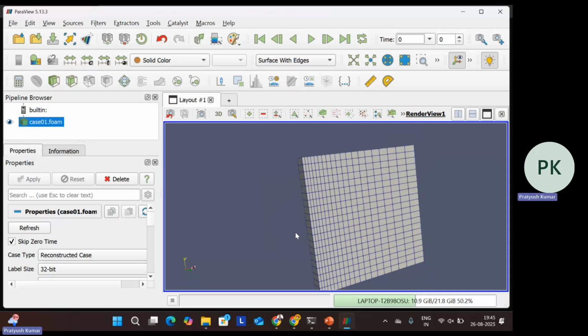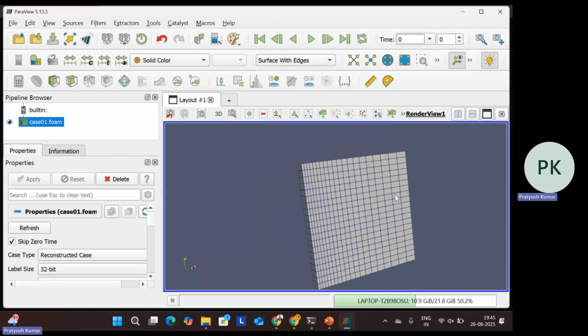No, edge grading is similar to simple grading. A slightly different technique is used, but both do the same thing. What you can do is simply take multiple blocks. We can divide this block into 4 different blocks. Suppose we have taken these 4 blocks, and we can use simple grading for this wall, then